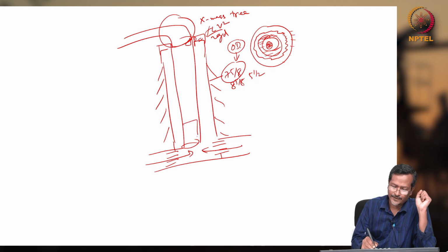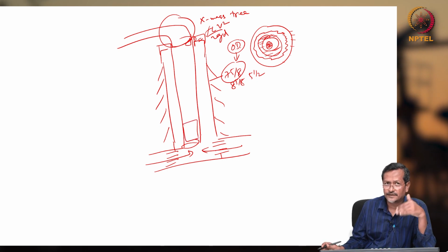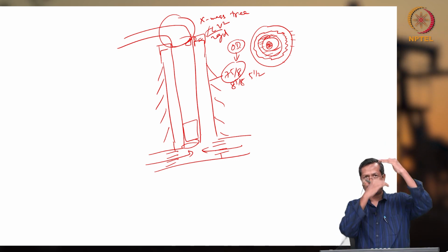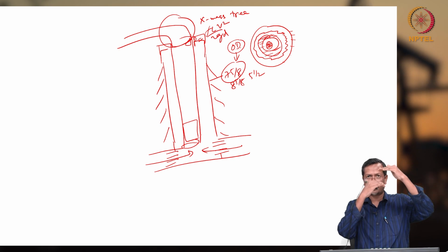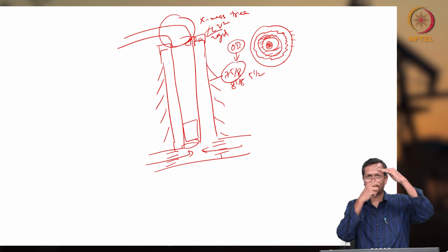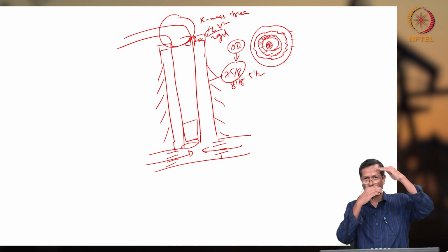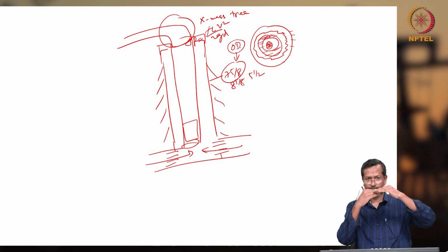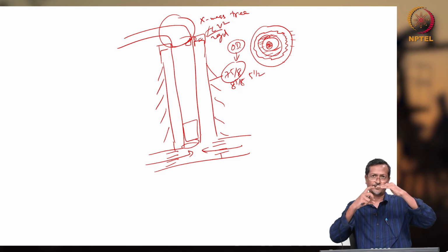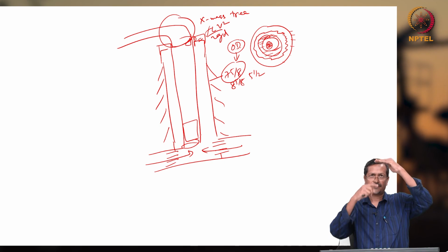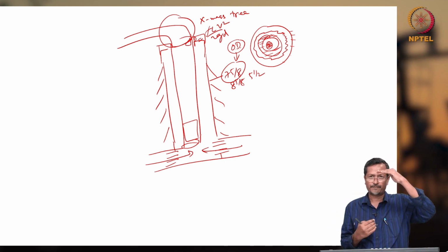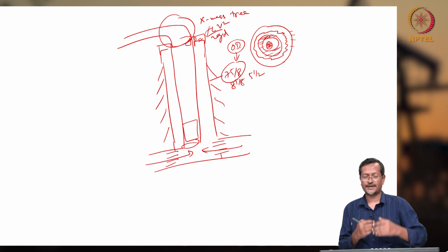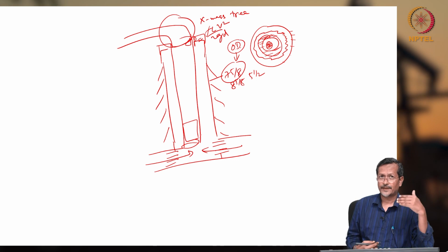And where will be the pump? Pump will be the nearby bottom area, and pump may not be at nearby perforations area, it may be below or up. If you are putting pump upper than perforation area, then you have to check how much head available, NPSH. If net positive suction head requirement is higher, then you have to bring down the pump height, then your NPSH available will be increasing. And if you are moving up pump, then NPSH available will be lower. So pump setting depth also you have to check, how much pressure is there in your wellbore. Accordingly, you have to check your pump setting depth, and how much pressure it will develop.